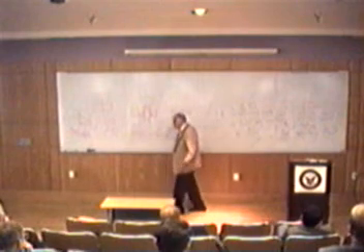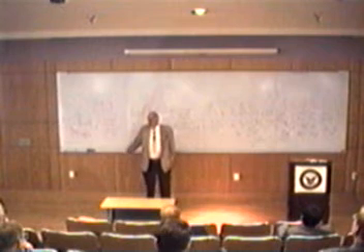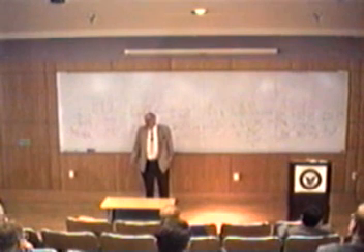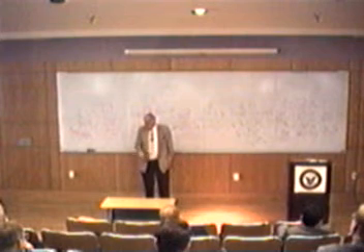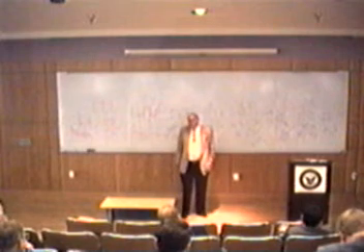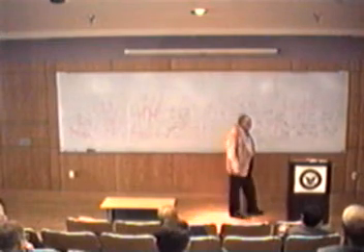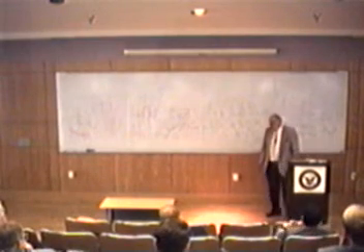Those numbers are beautiful numbers. So long as the computer runs, those are the numbers. And there's no temperature compensation. There's none of all those crazy things, or atmospheric compensation. There's none of that in running a digital filter, which were true in the analog ones. And the coefficients in the machine stay the coefficients. They don't change. Whereas in an analog filter, you build it today, tomorrow the constants have changed a little bit, and the next day they're a little bit further off. There was a whole different world which they didn't appreciate. I could get away with things like practically standing on my head and balancing because the numbers would not change. They could never have done it. So what they couldn't do, I could do.